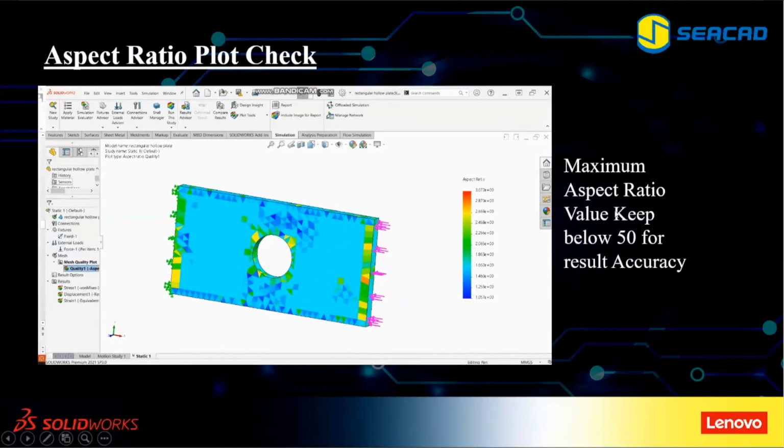The maximum aspect ratio should be kept below 50 for result accuracy. In this model, the maximum aspect ratio in the legend is 3.072, so we can say that the result will be accurate. This is one of the methods, the aspect ratio plot.